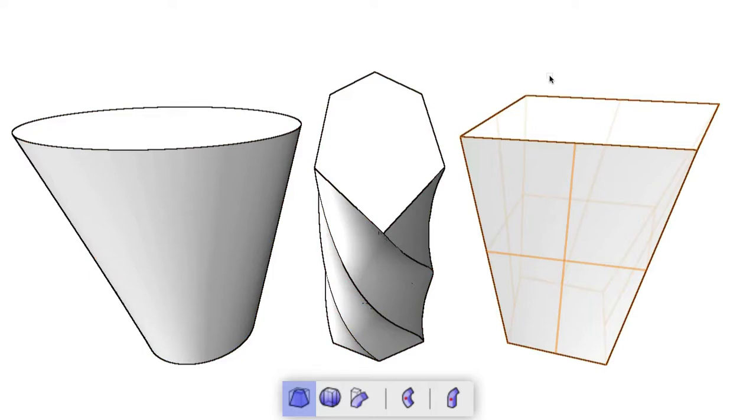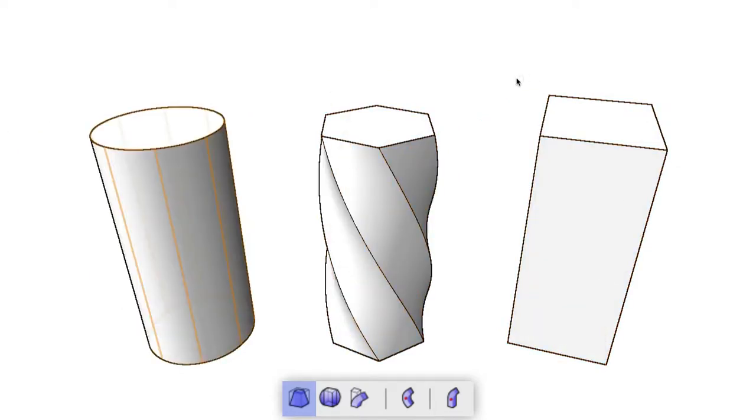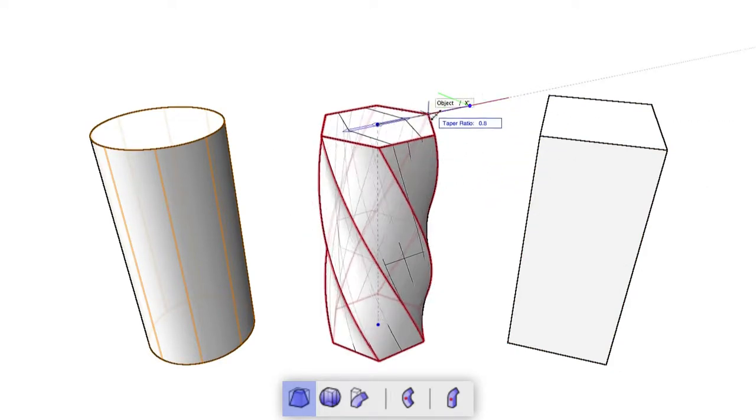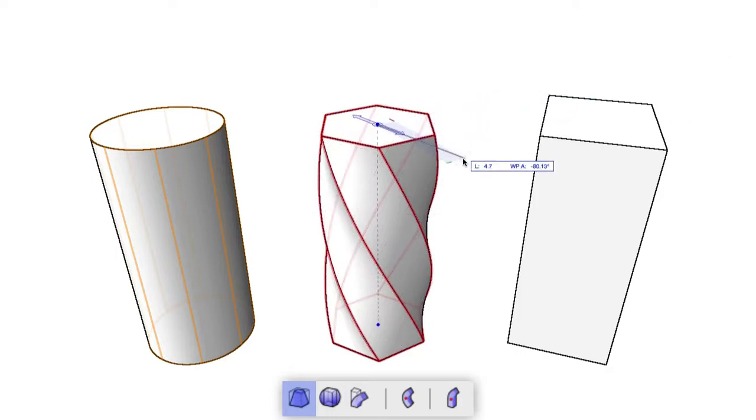After selecting the object with the Deform tool, the next click will again indicate the focus point of the taper, but now we must indicate in which direction we want the taper. This is set in the same click that determines the sensitivity of the Deform tool, as explained earlier. Now, when we taper the object, we see it being deformed in the two directions indicated by that arrow.